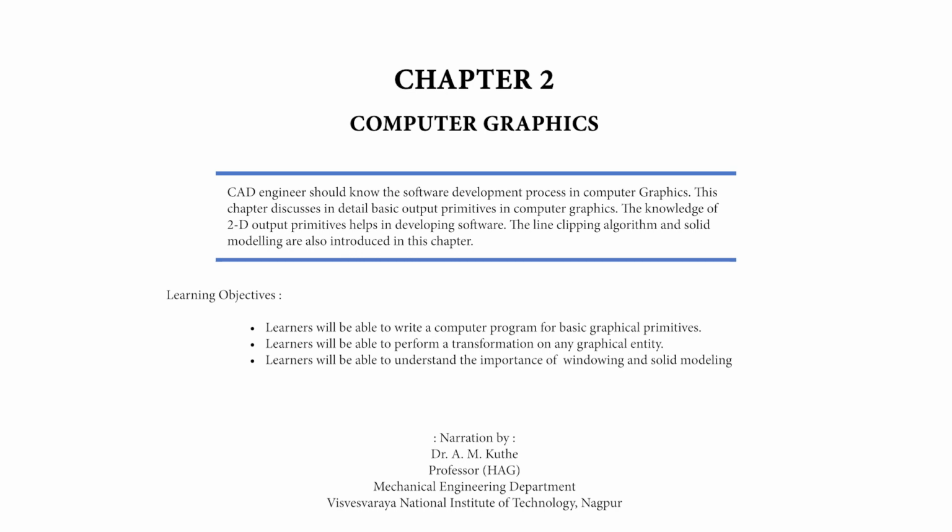A line from 2 points A (10, 30) and B (80, 70) is to be scaled by factor 1.5 in the x direction and 2 in y direction and to be translated by vector (30, 40). Determine the transformation matrix and coordinates of the transformed line.